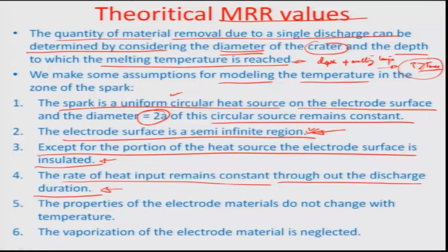Okay, so that finite time of discharge may be played around with very easily to obtain, at least for finishing processes, a very good estimation. For all practical purposes, we would assume the time of discharge to be so small, and the overall machining time to be so huge, that the discharge can be treated as more or less a momentary affair.